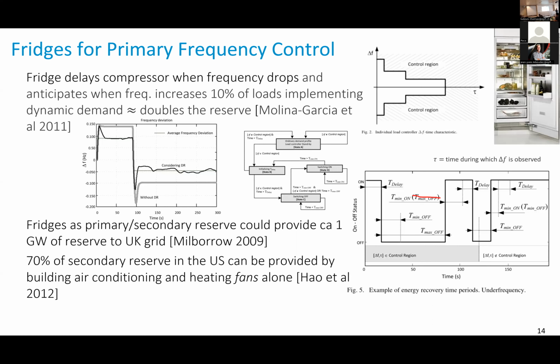So when they are closed and nothing is happening, the temperature decays or increases very, very slowly. If you put a small safety margin in the dead band, the temperature should be, for example, between 3 and 5. Instead, you want to never exceed 6. Then if you have a secondary margin that says the normal operating range is between 3 and 5, and now if I have a signal that says, well, perhaps you want to delay a bit, then perhaps I can go up to 6 here. So that's exactly what has been proposed.